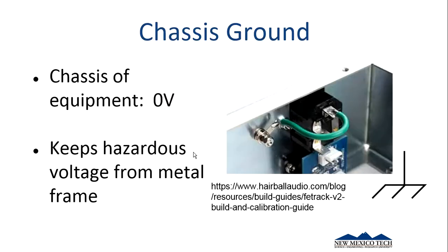And so that's kind of earth grounds, but what you'll maybe more commonly encounter are chassis grounds. What I mean by that is any piece of equipment that you've got inside of a big metal box, we'd like it so that when you touch the outside of the box, you don't get shocked. It would be a really exciting world if every time you went to turn on your computer, you got shocked. So what we do is, right here, you can see we've got this green wire bonded to the side of the box. And so what we've said is this box is basically a chassis ground, and there's our connection point for it.